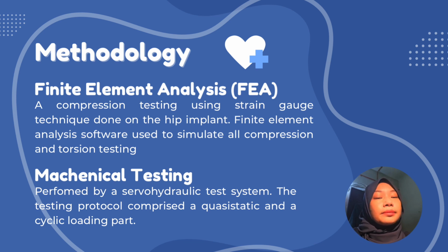The second test is the mechanical testing. The mechanical test is performed on a servo-hydraulic test system. Approximately, each specimen which has been obtained will be attached to the machine actuator via a ball and socket joint. The testing protocol comprised a quasi-static and a cyclic loading part.